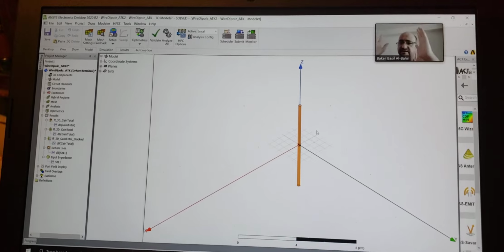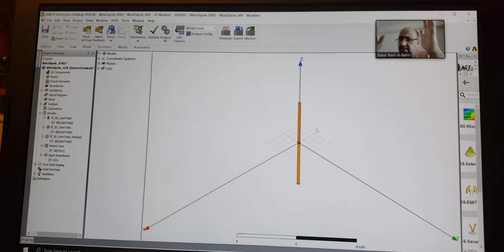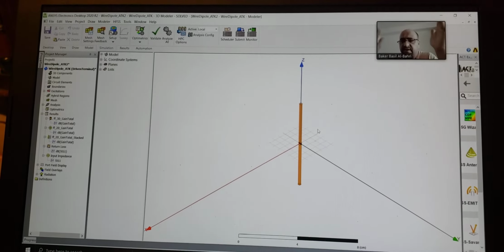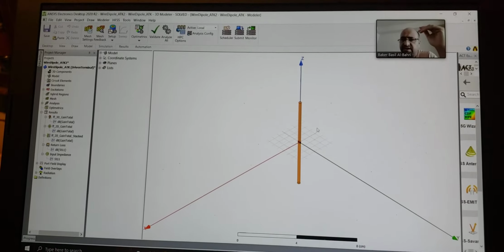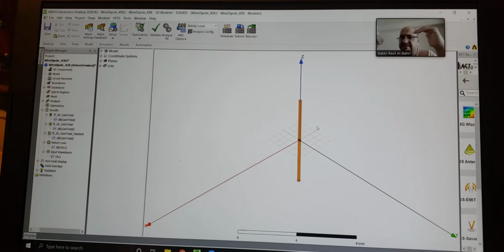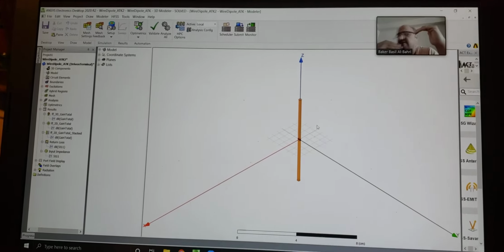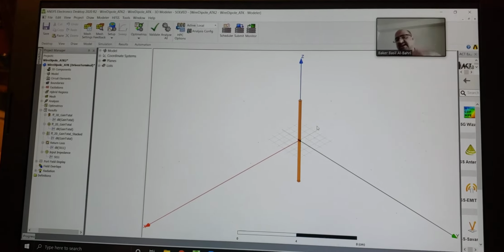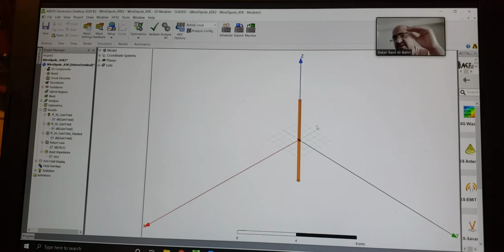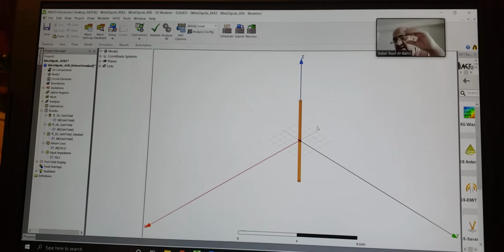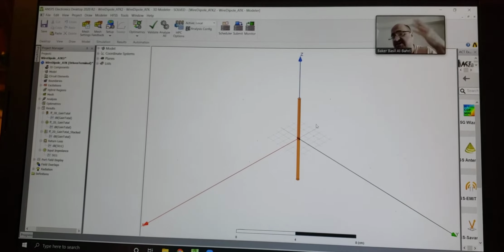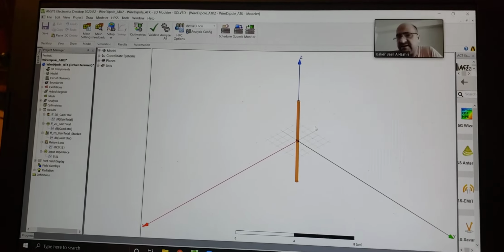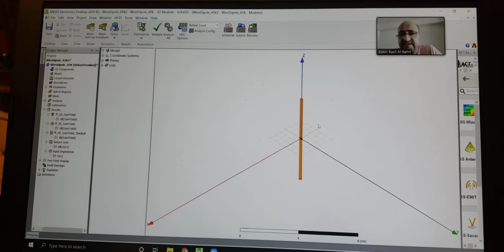So you have an electronic circuit in the transmitter. You have a signal, for example, your phone. Your voice is the first step. The output after the microphone is an analog signal related to your voice. Then this analog signal will be filtered, cleaned, and converted to a digital signal, because the mobile system is a digital system.